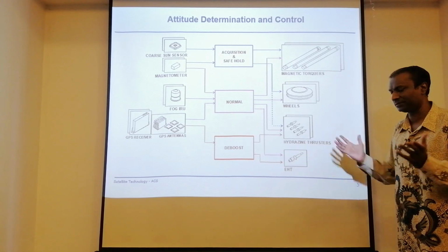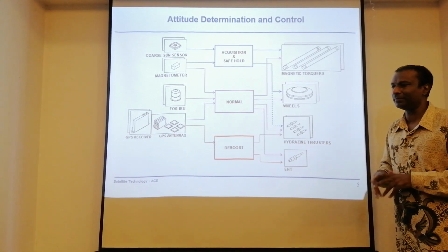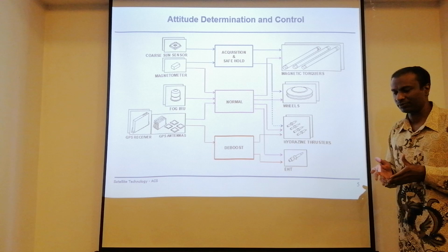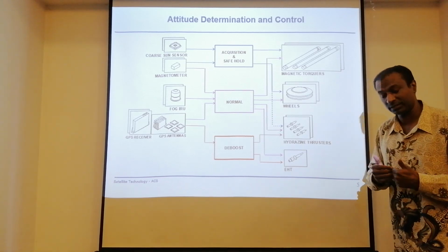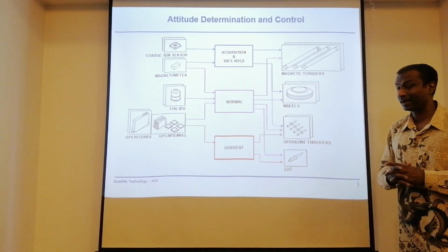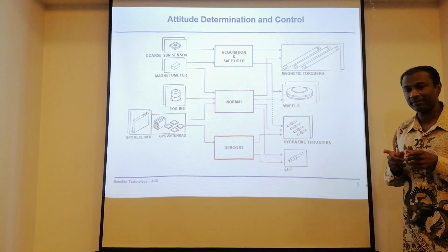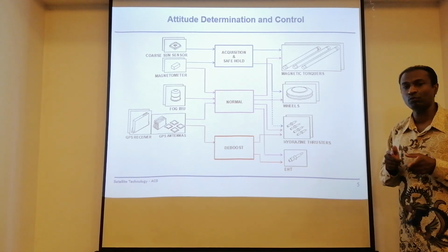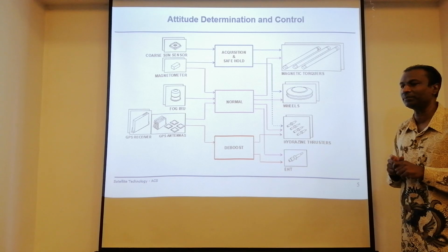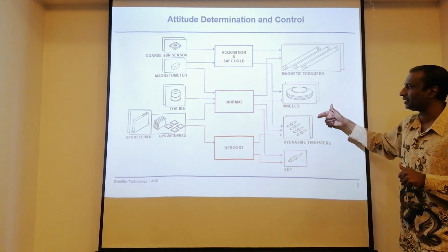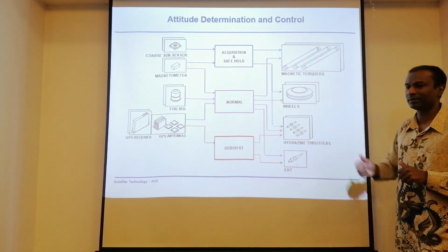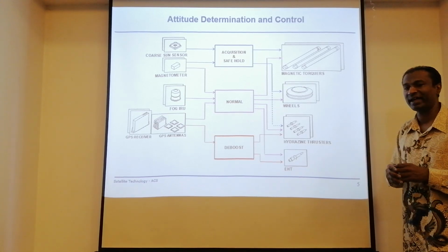So there are different sorts of thrusters, but in a nutshell, thrusters induce the translational motion primarily, but they can also help you to do a rotational motion if you want. But more often than not, we will pick the typical wheel, the reaction wheel or momentum wheel, to have the rotational motion.